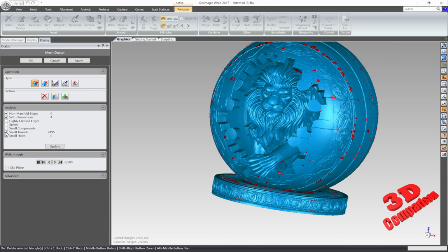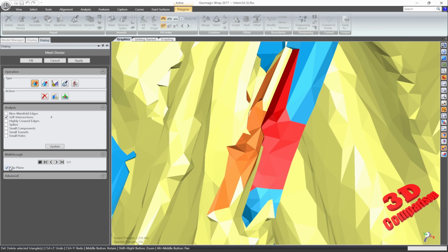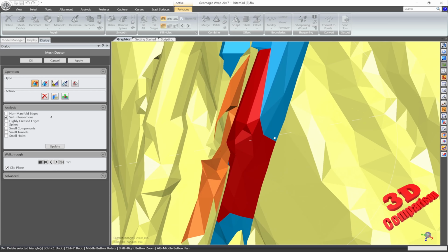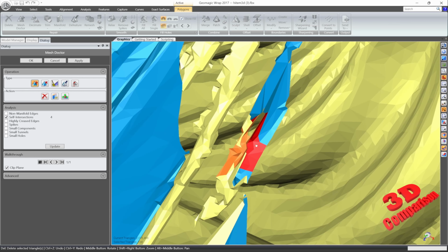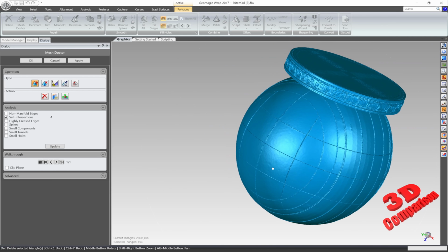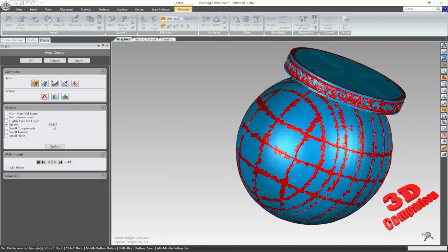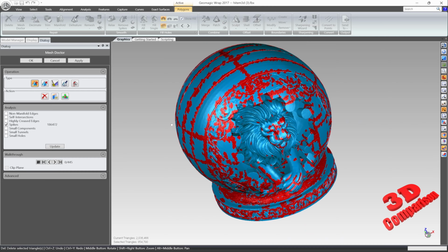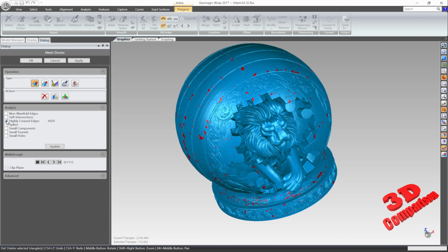So let's go ahead and walk through those in order to see those. I'm going to enable them, also add a clipping plane. Over here, we're going to have the only self-intersection within the mesh. Slightly over here, we're going to have those overlapping onto the interior. Regarding spikes, we're going to see a high amount of spikes. Since Hitem3D, in my opinion, outputs the best triangular meshes, it will also output a high amount of spikes, as we can see over here. So almost 4 times that number that Tripo generated. For the highly creased faces as well, so 7,000 faces.